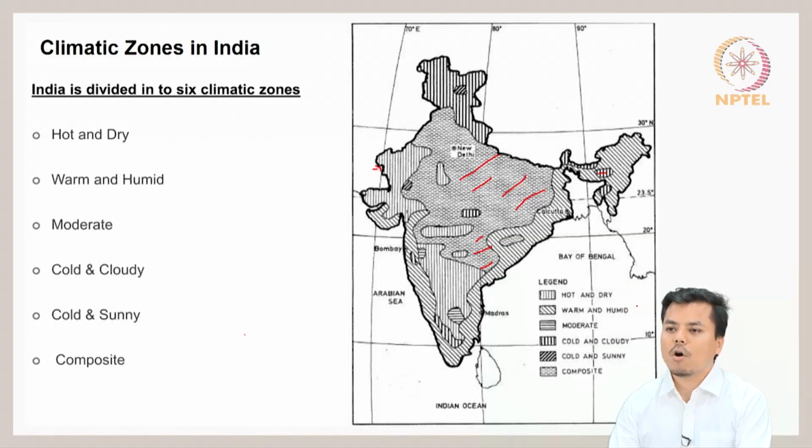And then the other is the warm and humid climatic region, which is seen in coastal areas. All these coastal areas here, even here Tripura, and in the northeast also. The temperature over there during summer is not that extreme, but humidity is the main concern. So, the design has to be such that maximum cross ventilation or air circulation is promoted in the buildings. Now we will focus on each of these climatic zones in detail and understand the design strategies.